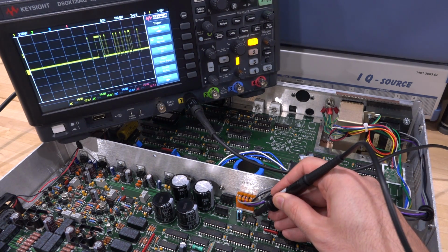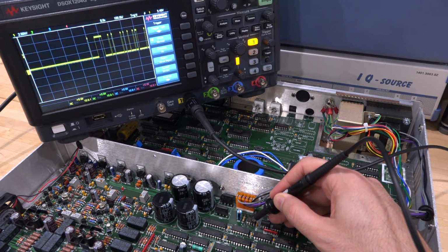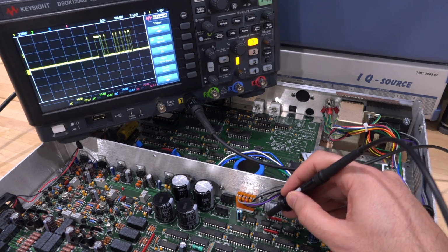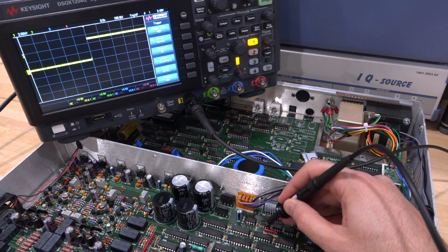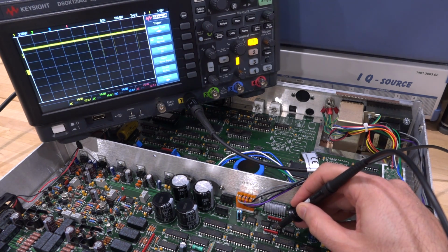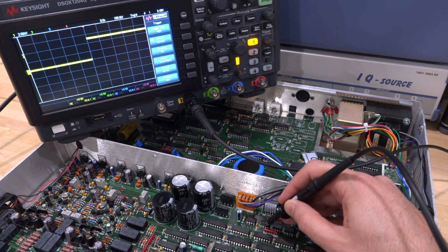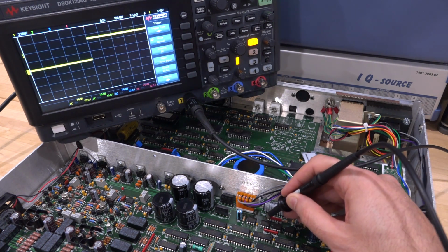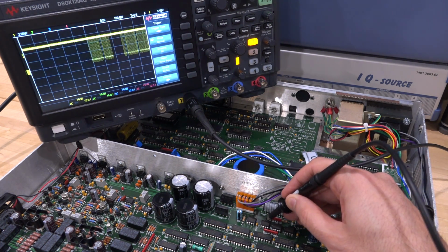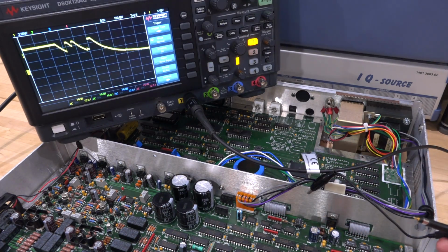Yep, this is data. Now if I go to the output side and I do the same thing, you can see I'm getting a really nice signal coming out of that one. And I go to the output side of the next one and I get nothing at all. The output of the third one, I get signal again. So the output of one of these optoisolators has no toggling, and that's actually the clock. But on the input side, it does. See, here's the input of the optoisolator. Here's the output of the optoisolator. Nothing. So that's already pretty interesting.